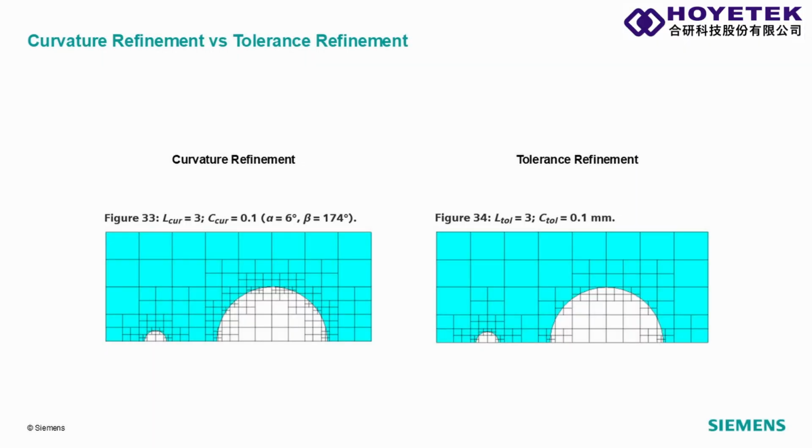The tolerance refinement may affect the same cells that were affected by the small solid refinement and the curvature refinement. However, it resolves the interface's curvature more effectively than the small solid refinement, and in contrast to the curvature refinement, it discerns small and large features of equal curvature, thus avoiding refinement in regions of less importance.